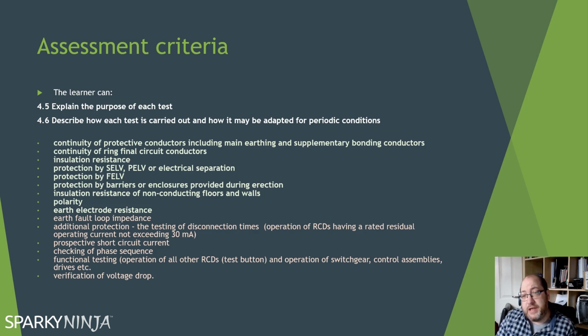For the periodic condition, as we saw on the prior video, you may not need to do ring final circuit testing. It's considered that if you have existing maintenance and there's no changing or alterations, then you may not need to do it. If you do choose to do it, then you'll obviously have to de-energize the circuit, but you may do it at one point and then just sample the other points.